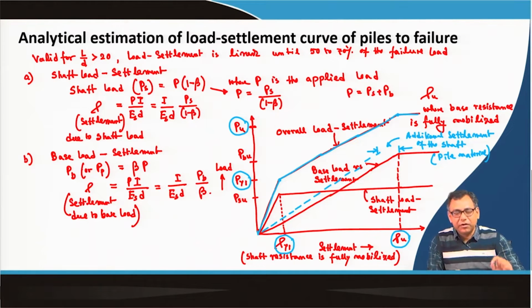During that moment, the deformation of the pile material will not take place. So, up to this blue line, this is the deformation of the soil due to the tip load. Then once it is done, the deformation of the pile material will take place, and the overall deformation of the pile material plus soil due to the tip load is this red line.